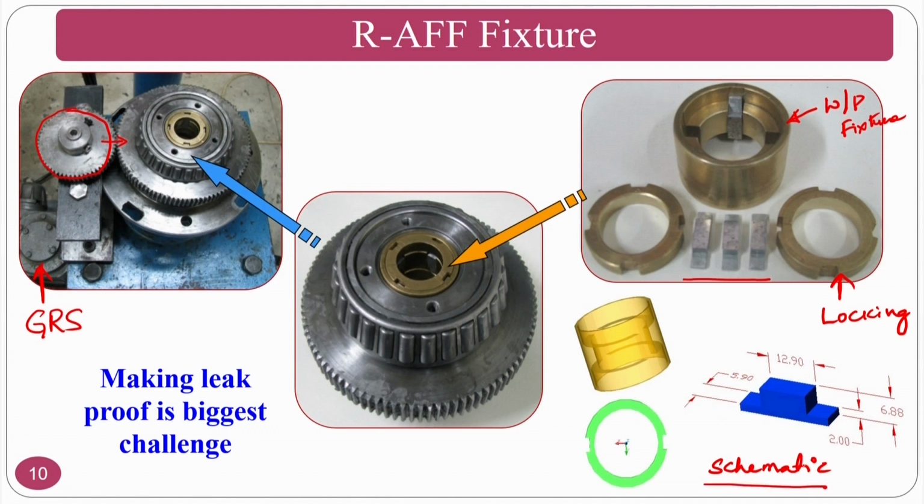Okay. The most important thing here, whenever this system is going for a patent and other things, is the leak proof system. How you make a leak proof system is the most important thing in this particular rotational abrasive flow finishing, because most of the system is under static conditions, and only the workpiece region is in a dynamic condition. That is why, in most of the advancements, if you see the centrifugal force assisted as well as the spiral polishing and other cases, the medium is given the dynamic motions, not the workpiece.